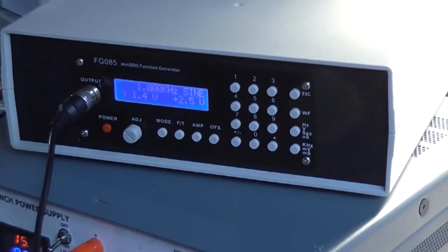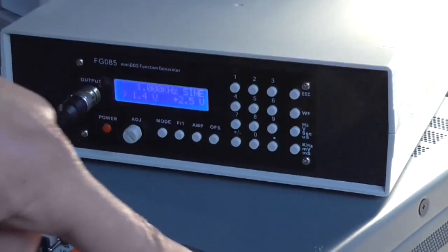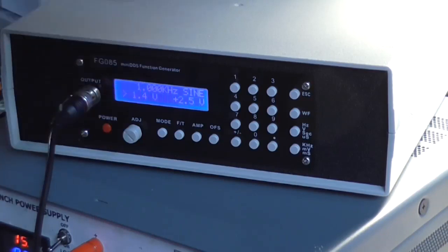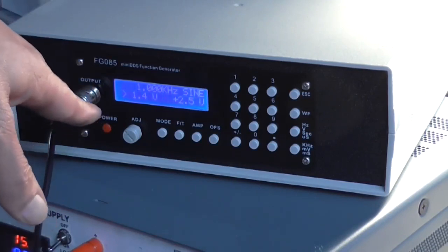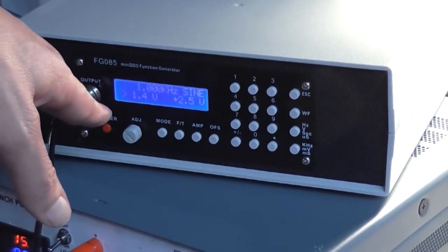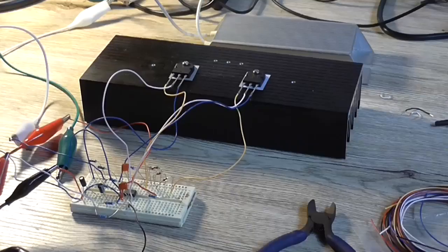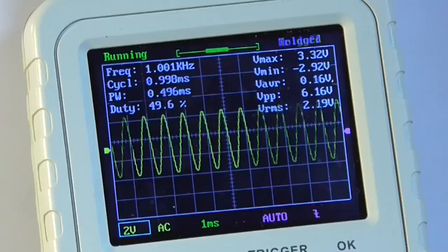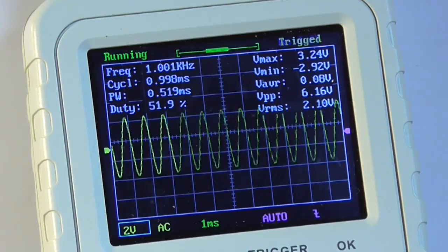If you increase the gain of the amplifier, that means its input sensitivity, the amount of voltage you can put into it, is going to be lowered. So the higher the gain of the amplifier is, the lower the input voltage needs to be to give it full output. So increasing the gain would not gain us any extra power, because we're still limited to the plus minus 15 volt rail. However, we're not swinging anywhere close to that plus minus 15 volt rail.